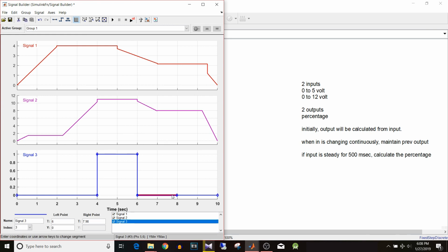What you have to do is select the signal and shift, then just click where you want this point. Then select the section of the signal that you want to change. I want to modify the values from 6 to 8, so just change this, select this one and give whatever value you want. I want this to be equal to 0.6.